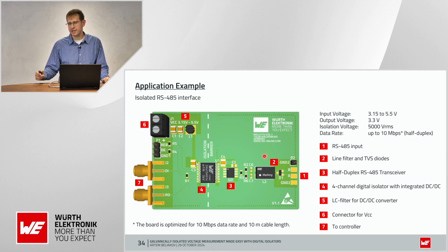As you can also see, input voltage will be between 3.15 and 5.5 volts, output voltage 3.3 volt, and isolation voltage up to 5000 volt RMS according to the UL 1577 standard, and as I already said, data rate up to 10 megabit per second.